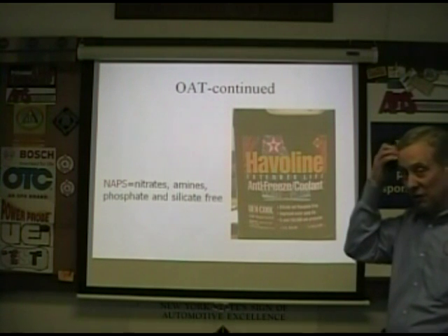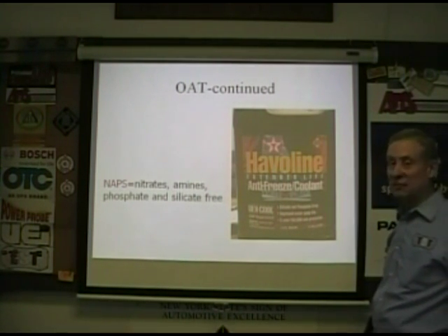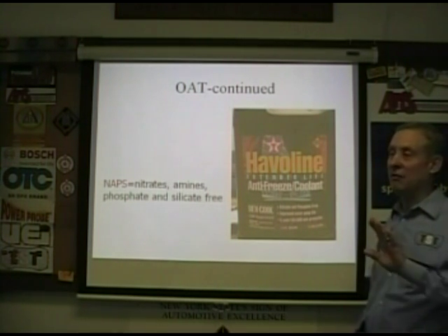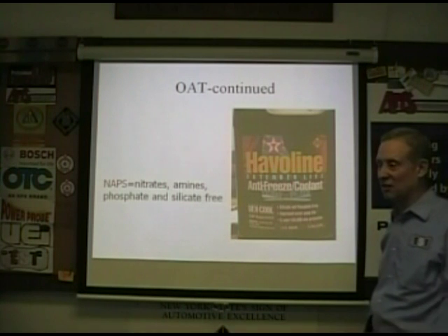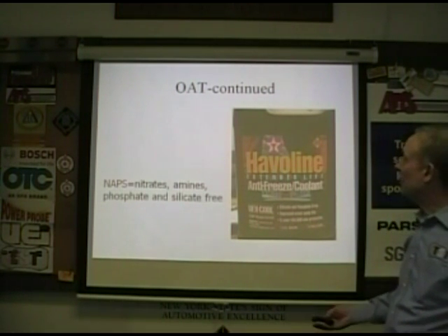I saw an engine once that looked like it had wormholes through the head. Massive coolant incompatibility, and some other shop had put that head on 1.5 years earlier. It was a brand new cylinder head on a BMW with holes in it. Very nasty.